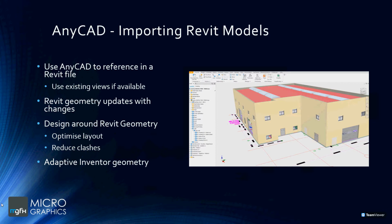The Inventor geometry can also be linked to that Revit geometry. What this means is that there is less rework for the Inventor user if the model is updated. So in that balcony example, if the size of the balcony or the opening where the balcony is attached to changes, your design of the balcony can adjust around that change in the Revit model.